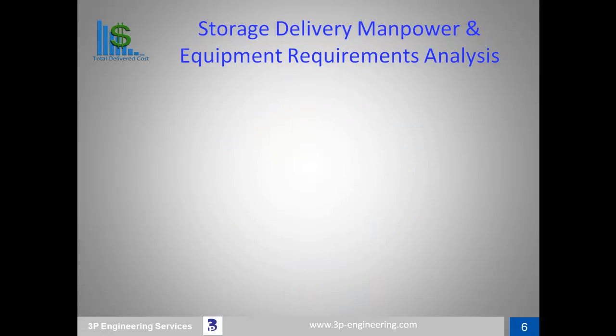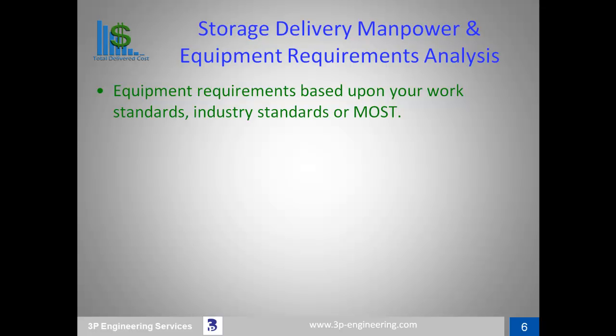Equipment and manpower requirements are estimated for each piece of equipment within each circle of work. Typically, forklifts are utilized for this type of work. However, if automatic slug unload equipment, SGVs, or AGVs are utilized, they will be grouped into unique circles of work and measured accordingly. In the case of forklift drivers, we generally assume that there will be one person assigned to one truck per shift. If that's not the case, adjustments are made based upon your work patterns.